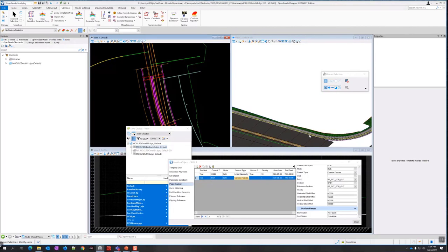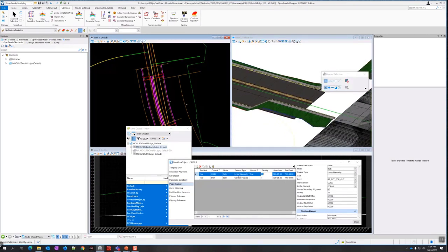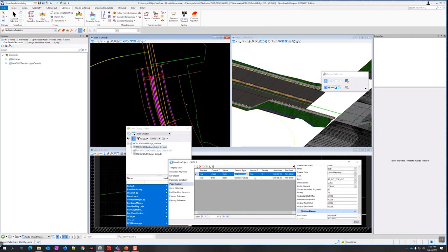So for some reason it thinks they're overlapping, so the priority conflict. It shouldn't be, but if in doubt, we can do it this way. So this one would take precedence, and wherever this one doesn't apply, this 10 now is the lowest priority, so that takes precedence. So that's something that does come into play when you're working on the same point. So the best bet may be to set the priorities different for those two.